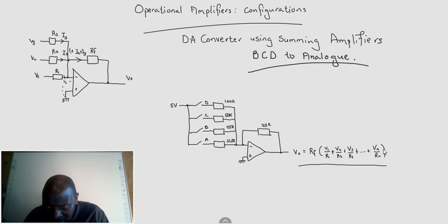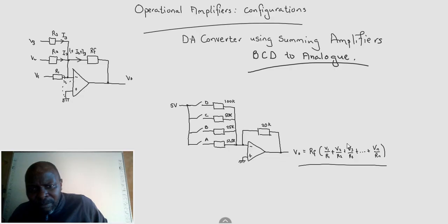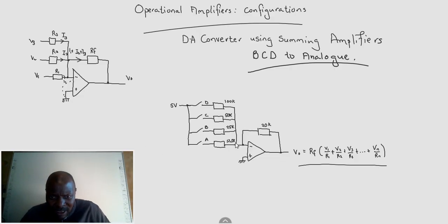If there is more, like I said, in the general case, maybe let's say n, any number, then you'd add all those currents. Remember, this is from Kirchhoff. All these currents coming to this joint will be added together to get the input current. Remember, the input current is whatever comes in here, which is going to be rejected by the op amp and sent through the feedback. So our I total is sent through the feedback resistor.